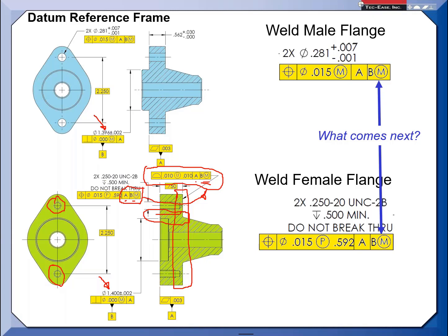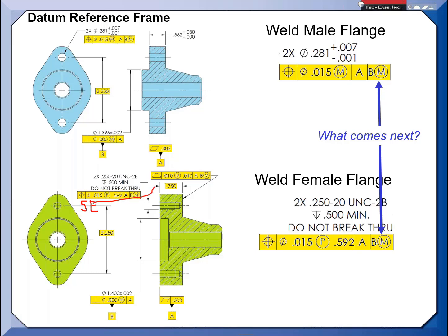Now, if you didn't want that, what I could do in this case is come underneath here, and the standard says, hey, Ed, I want these checked separately, even though I have the same datum. You can put in what we call an abbreviation, separate requirement, and put it on both. Now I can do 2 totally different checks. I could still check them simultaneously if I wanted to. If they meet that, then I'm done. But if one of these is out relative to the other, then you're back to the separate requirement.